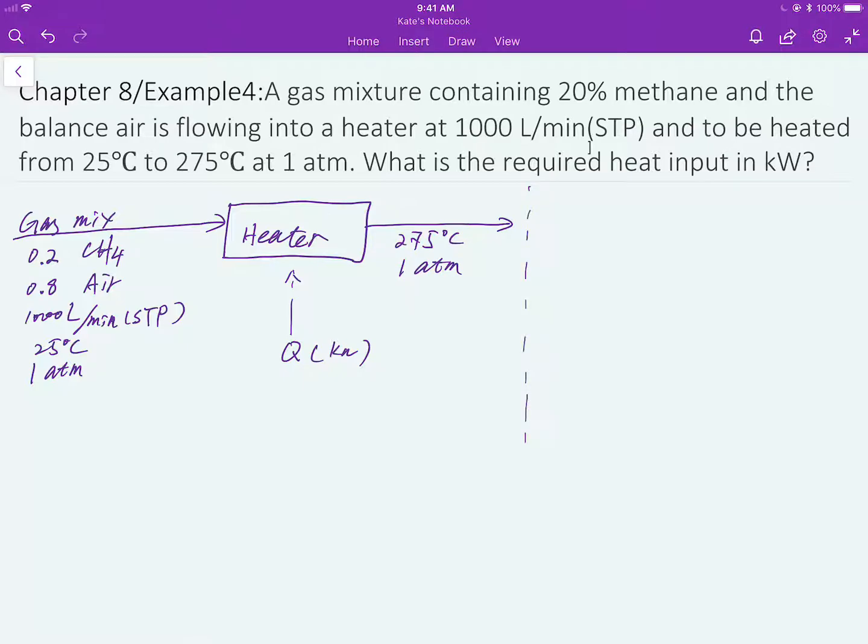Well, from there, I can write down assumptions to let people know what I'm thinking to run my calculation, and this way I can cancel the terms that are negligible for the energy balance equation. First of all, this is a heater, not a reactor, so there's no reaction. It's a non-reactive process. I just simply say no reaction. And given STP, based on the condition given, I can say this is ideal gas. And the heater has no turbine, so I can say there's no shaft work.